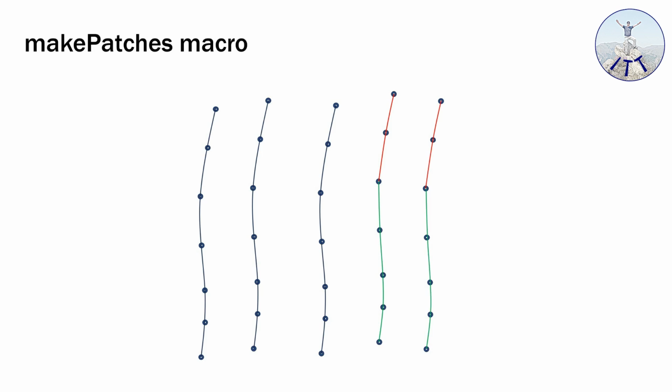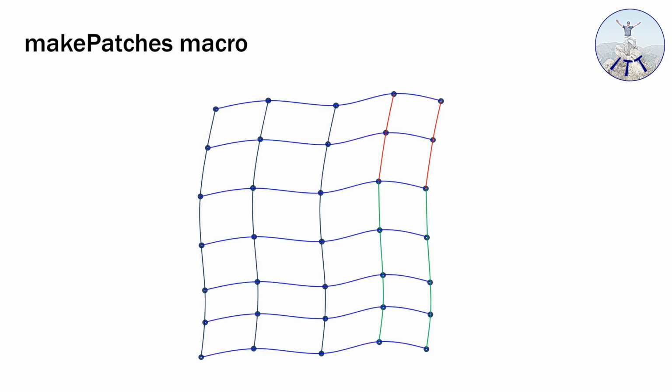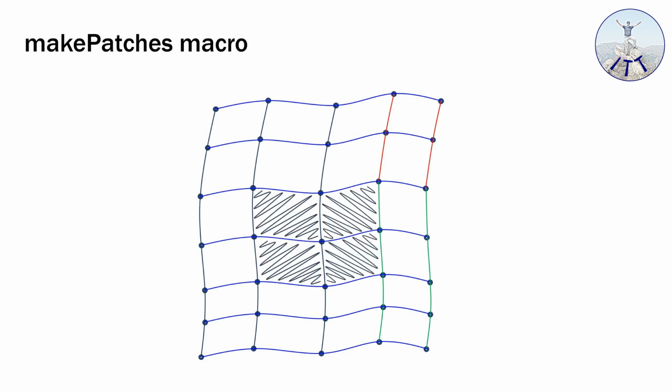Then we can do the same thing in the rib direction. So we just define the curves that we want in the rib direction. And then those can also be split if we want them, or continuous curves with continuous slope all the way along the curve. And then we define which patches we want in that topology. We don't have to have all of the patches, we can select individual ones or certain areas. But we must define curves between all of the points. We can't have any gaps between points.